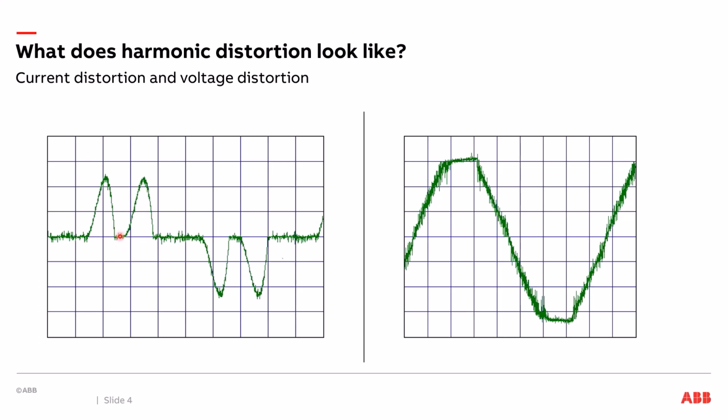This particular drive doesn't have any kind of harmonic mitigation at all. If you started adding reactors, this hump would not come down nearly as low at full load. It would be more along the lines of that. So you can add impedance to mitigate harmonics. There's a lot of different harmonic mitigation solutions.